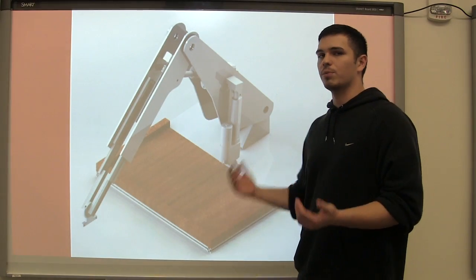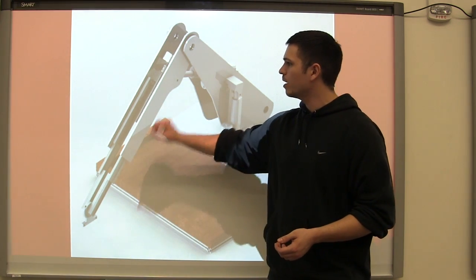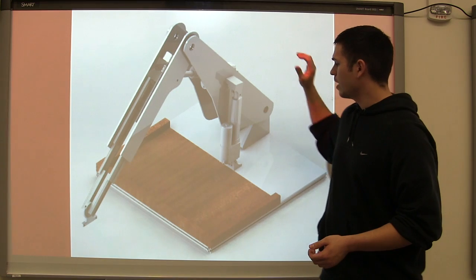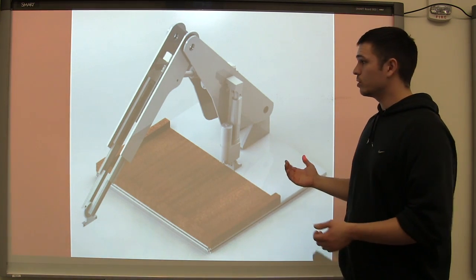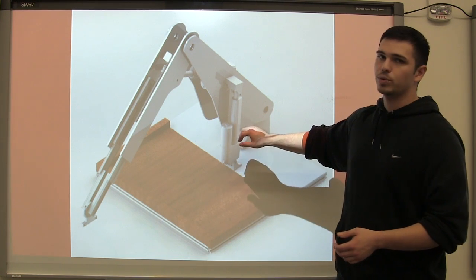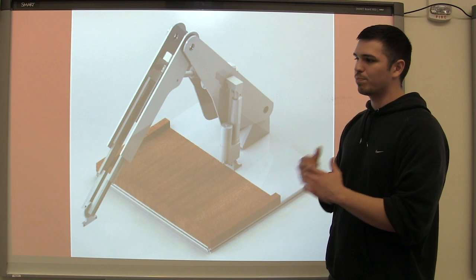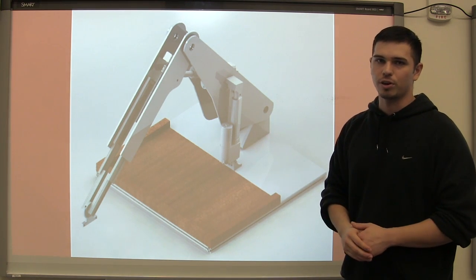We used what's known as sum of the forces analysis, where we broke up this model into a telescoping arm, second link, the first link, and the base. By doing so, we were actually able to find out that this first linear actuator would cause link 1 to twist in a way that would break our entire model as soon as it would start.